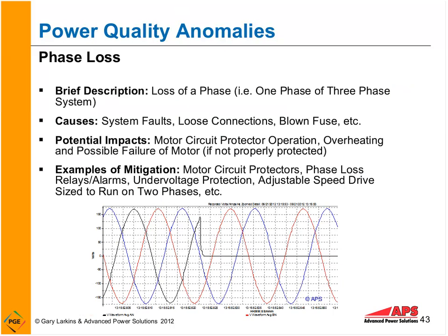Let's say a tree limb got into a feeder and it blew the fuse on that phase. Or we had a fuse in our facility. One of the legs in our facility has a fusible disconnect. The fuse blew because of a fault in the cable. So if a phase goes away, we have 2 phases left here. And what this can do is